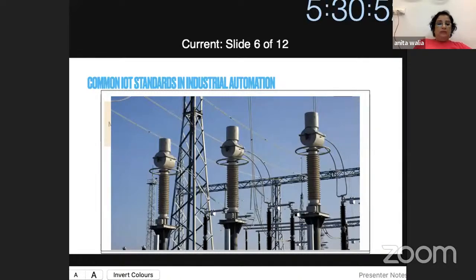One of the common Ethernet based standards for communication in the industry, in the power generation industry especially, is IEC 61850. It is the standard regulation for communication between different equipment in a substation, for production control, and for measurement of the equipment, or an intelligent electronic device, IED. All of those use the IEC 61850 standard. So that's a quality standard every company needs to follow.